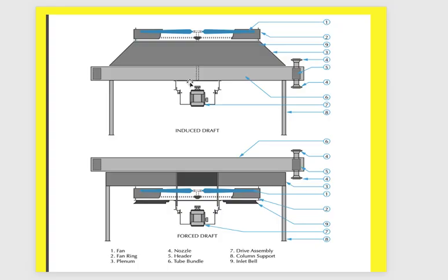Vibration damper and bearing, the function is to reduce the vibration and ensure smooth and safe operation. And for sure, number 12, the instrumentation auxiliary, like monitoring the temperature itself, controlling and monitoring the vibration, motor current indicator, and in some cases measuring or inspecting the air flow.